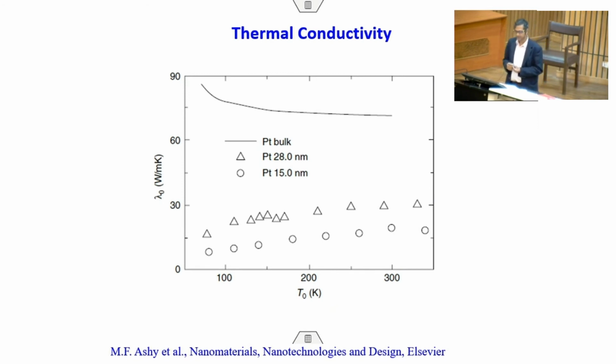So all are possible. As you know, nanoporous materials are used as a dielectric material in the microelectronic industry because of their low dielectric constants. Okay, because the moment you use a pore, dielectric constant will go down. However, the thermal conductivity is also low, which can cause a serious problem for these dielectric materials. So let us start with the single layer nanometric materials.